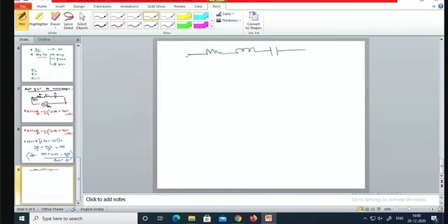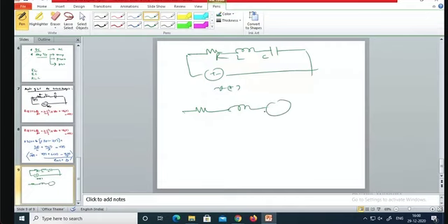So you have to represent the circuit in Laplace transform, RLC, like this, V of t. So this is R, and you write an inductor and you have to represent its initial condition by some voltage, that is L into I of 0 plus, or 0 minus. So this together is the initial condition representation of the inductor.